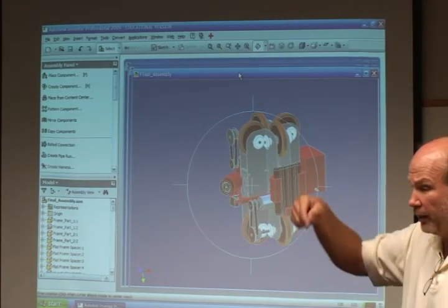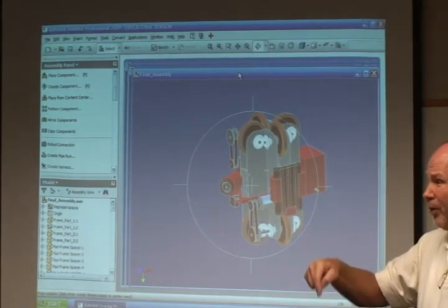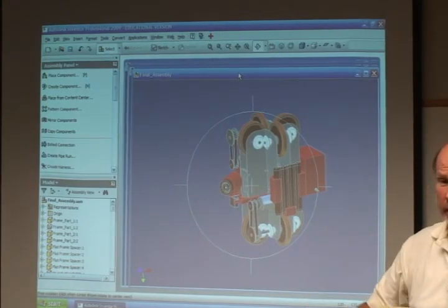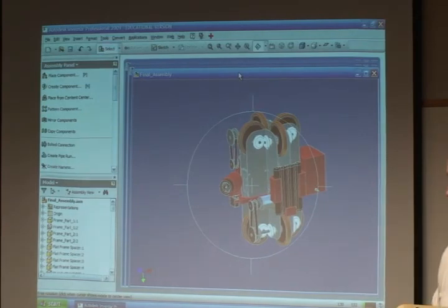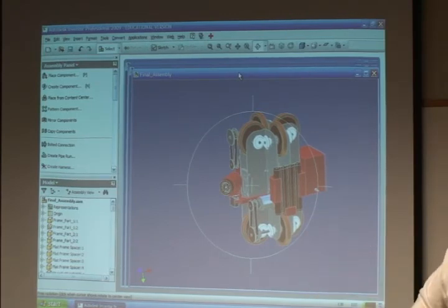All it required is drilling a hole down through. I'll show you some pictures later. They have a hole so you can put an Allen wrench down there to tighten that set screw. So little things that will save you a lot of aggravation and maybe get you a championship someday. I strongly recommend prototypes, whether they be wood or cardboard. If you have access to an engraver, it's a real easy way to make up a prototype.